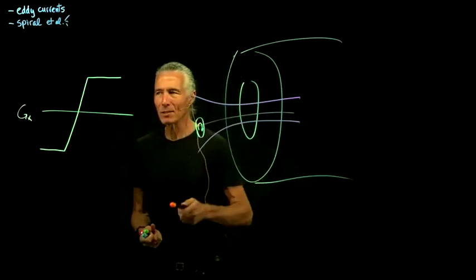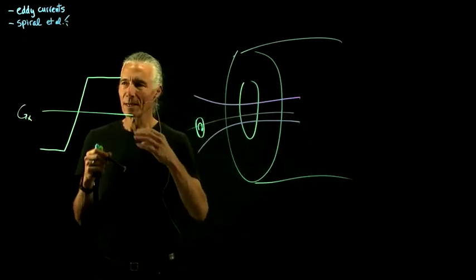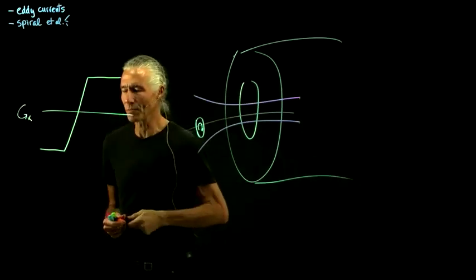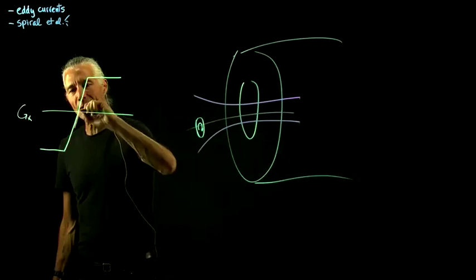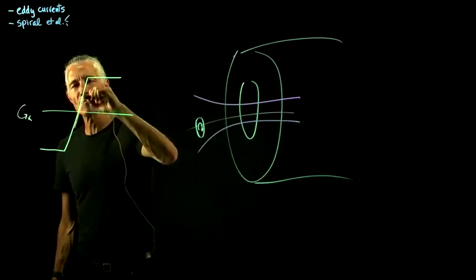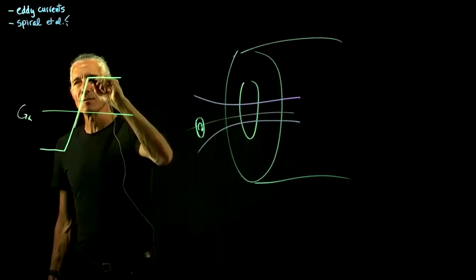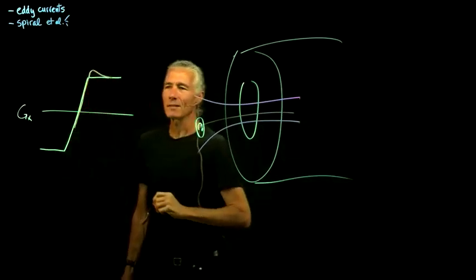what will actually happen if you measure the magnetic field that came out of the gradient coil? You can put a sensor in there and figure out what the gradient coils actually did. When you're on the straight, it's not too bad. The measured magnetic field will be about right. But when you suddenly go to a constant current through the gradient coils, you'll get something that looks like an overshoot.